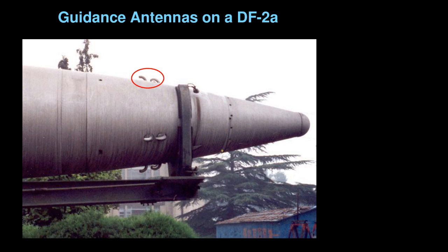And especially for long-range missiles, if you can do sensitivity analyses and you can convince yourself that if the angle and the speed are uncertain by a certain amount, by the time you propagate that error over mid-course phase and down into reentry, that can lead to relatively large inaccuracies. And so typically what you will do with a liquid fuel missile is you'll do it in two stages. You'll first drop the thrust level to sort of 5% of the full level. That gives you some fine control, and you can fine-tune the speed and the altitude, and then you terminate. So again, that's a step that you go through to try and control the termination of the thrust.